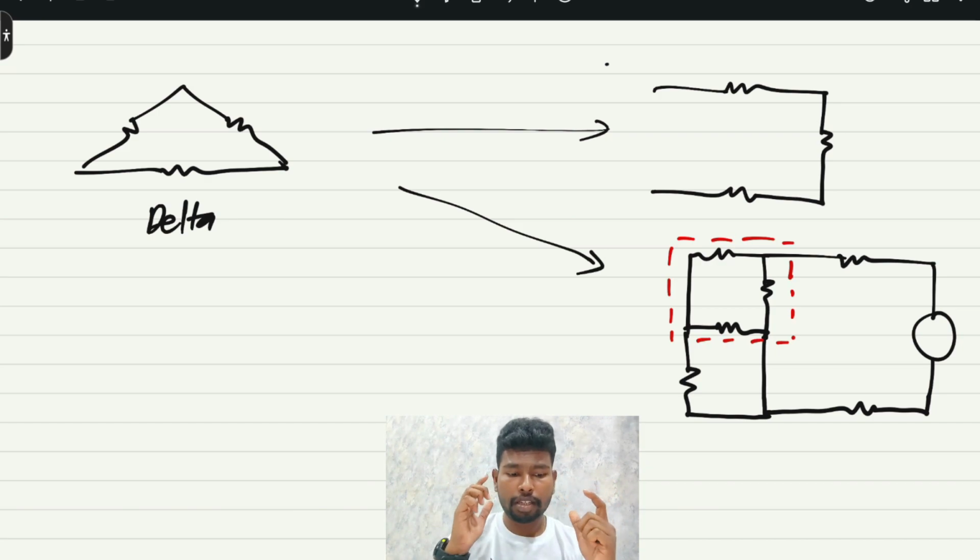Be analytical. You should analyze the circuit before you begin to solve, or you can rearrange the resistors across the circuit so that you can actually solve the problem. Simplify the circuit first. Remember, always simplify the circuit before solving any problem.